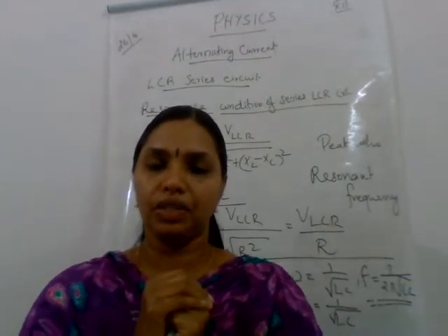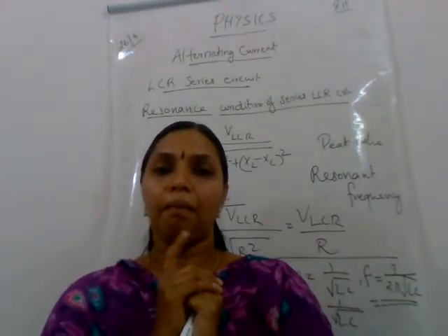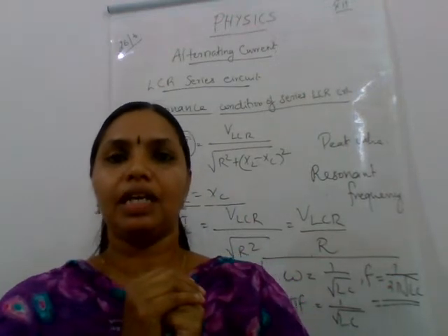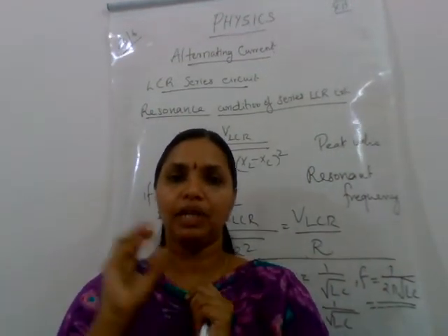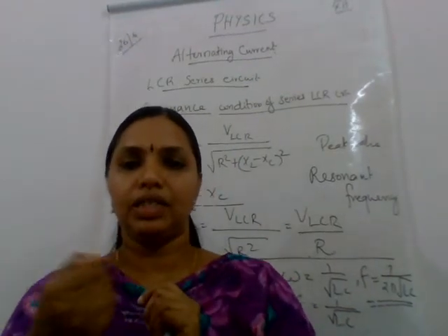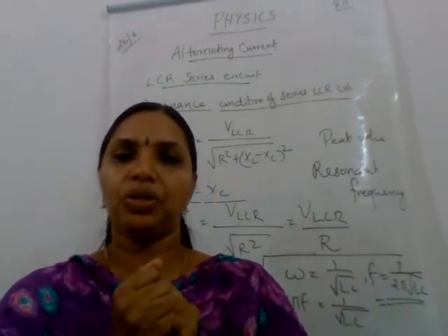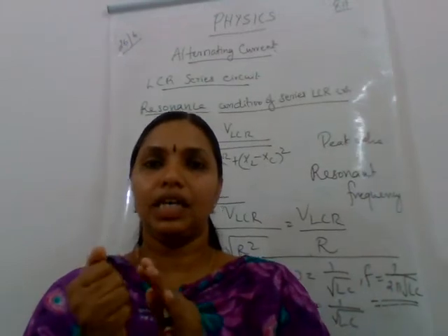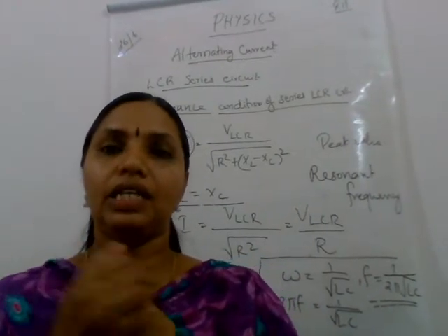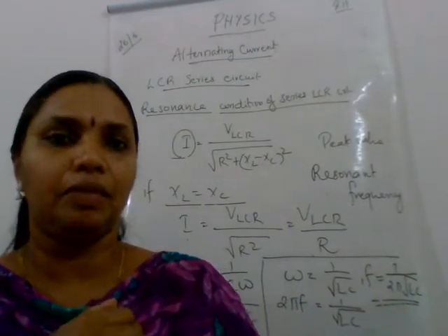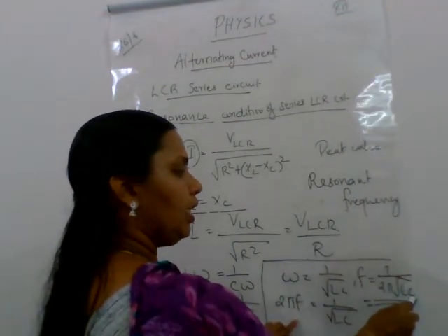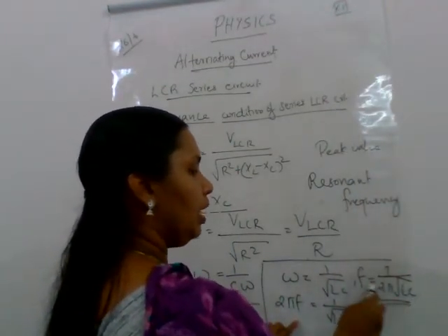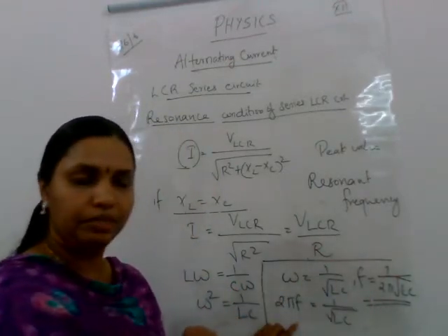The tuning circuit consists of a parallel connection of an inductor and a variable capacitor. While turning the knob, or adjusting the channel, what are you doing? You are just adjusting the capacitor, changing the value of the capacitor. Once you change the value of the capacitor, look at the equation: as C changes, this frequency changes.